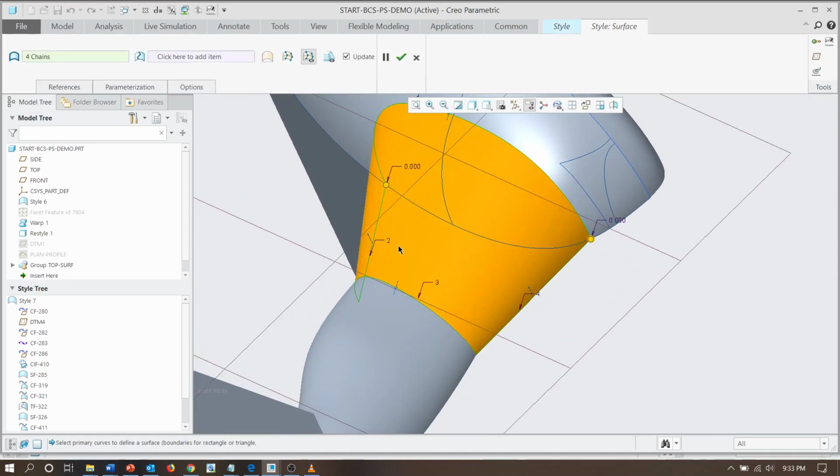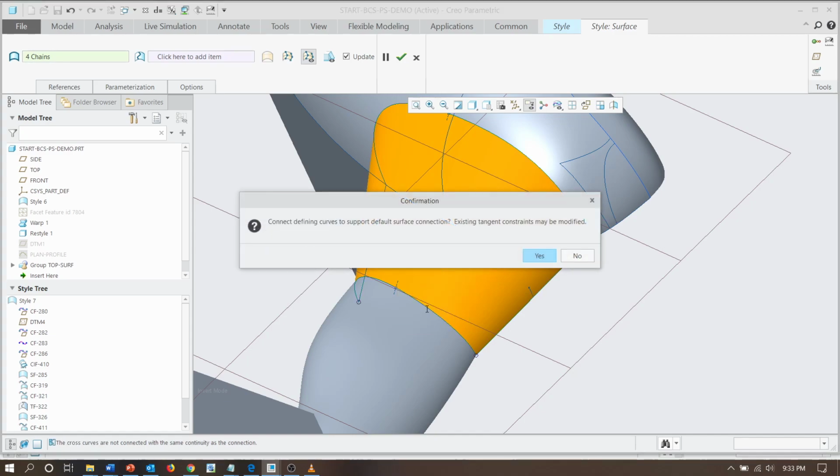So let's edit this. Now, similar to a regular boundary blend in base surfacing for Creo, you have icons. These are a little different, but it's the same thing. If you right click, you get your options: G0, position, tangent, and curvature. We're going to go straight into curvature.